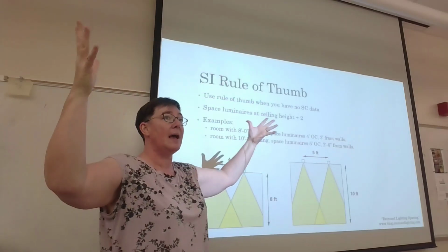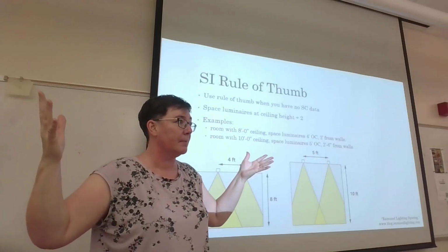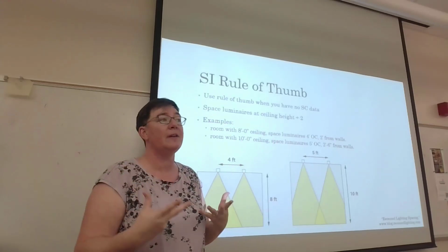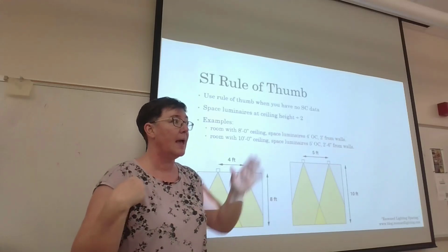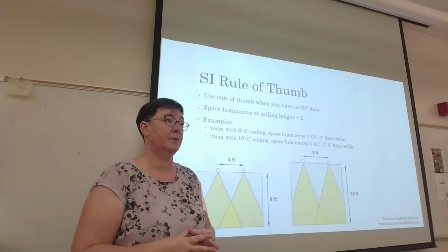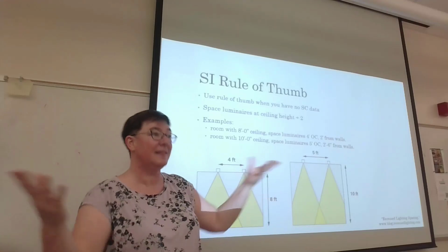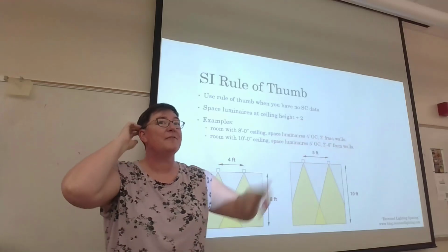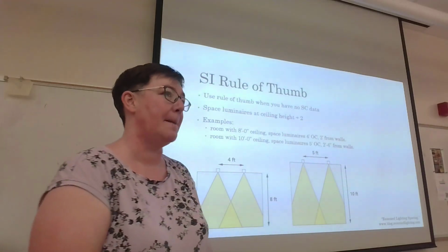You've got a residence with one room that has a 12-foot ceiling, and you're proposing to light it with a series of evenly spaced recessed can lights. What is your spacing interval? How far apart would you place those? 6 feet. 3 feet from the walls. Thank you. Yeah. So use the divide by 2 again.